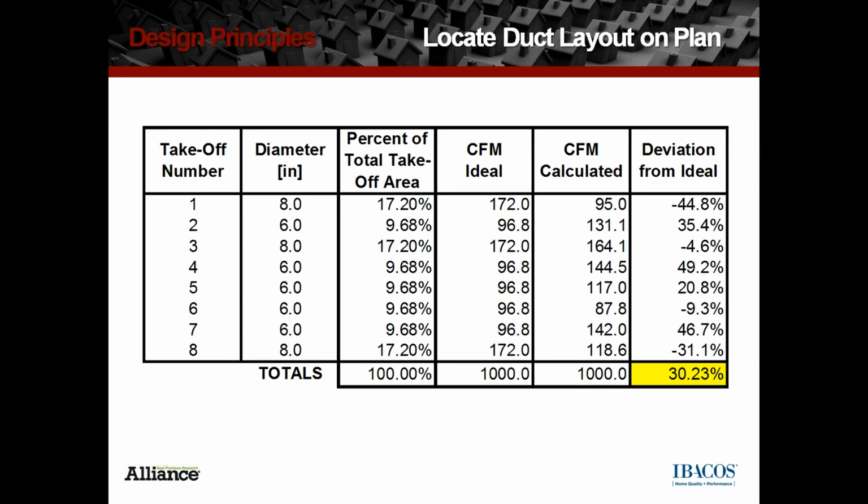But this is how that setup performed. There was a 30% variation between the designed CFM and the actual CFM as it was delivered to the rooms.